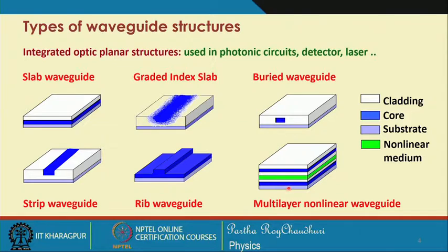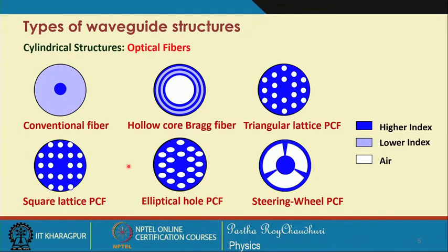which are very common in optoelectronic devices, gallium arsenide, gallium indium phosphide. So, these are of very particular importance in optoelectronic devices. But this is a step index profile, these are all step index profile. This is the one which is graded index profile, and most of these waveguides are very often used in integrated optics and photonics.